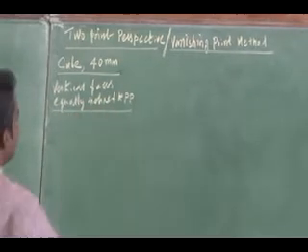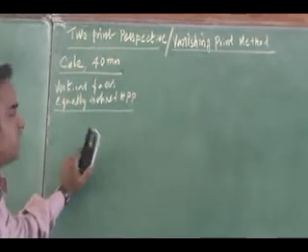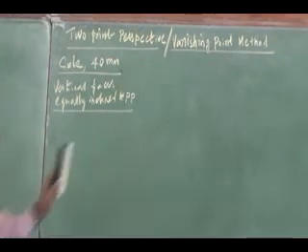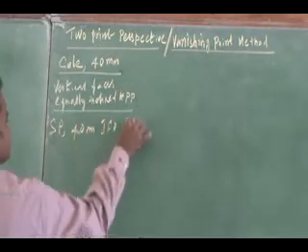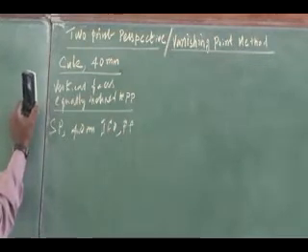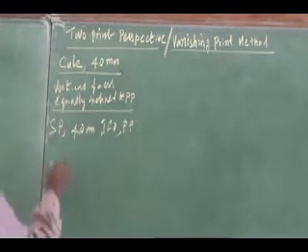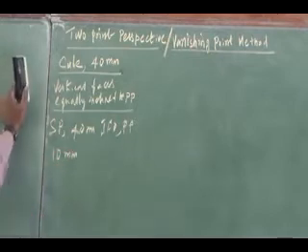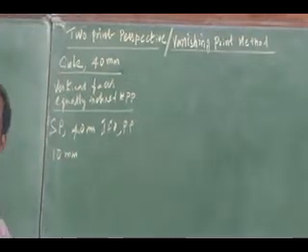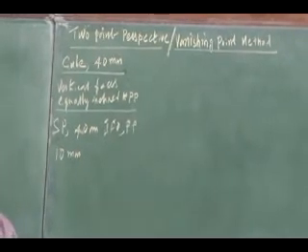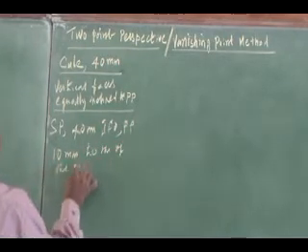So now, the vertical face is equally inclined to the picture plane. The station point is 40 mm in front of the picture plane, and 10 mm to the right of the nearest vertical edge.